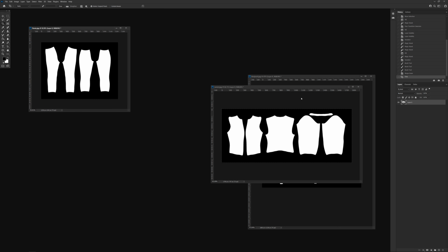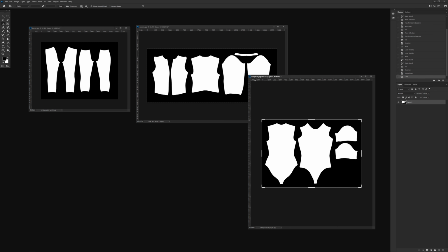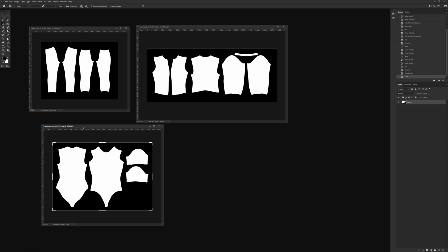Now, when you create, as we have, our characters out of a Z-sphere inside of ZBrush, inevitably what happens is that the length of time that you clicked and dragged to create that first Z-sphere. So when you clicked originally and you dragged out that initial Z-sphere, or drug out that, I don't know what the past tense of drag is. But if you were to create that Z-sphere, however long it took you to drag out that Z-sphere is the scale that you've imparted into that geometry. And so that is going to mess up with the scale of our objects.